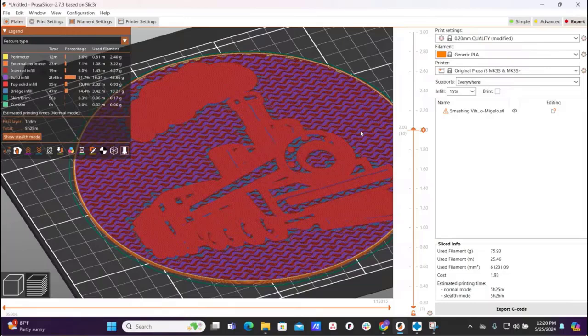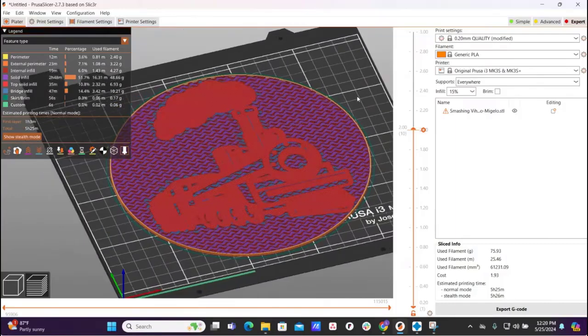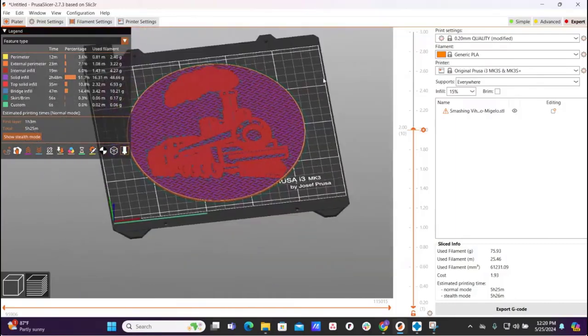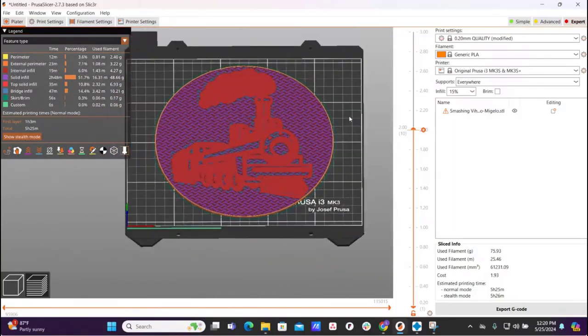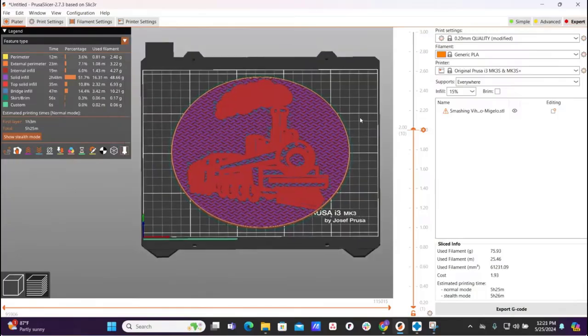You shouldn't have to worry about it right now. 15 typically works for everything, and a lot of the stock slicer settings work for most things. So again, to simplify it and make it easy, just print with how your profile is set up, with what the manufacturers have already established, and only change it if it's not working for your process.